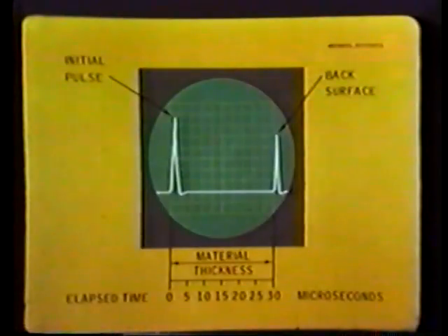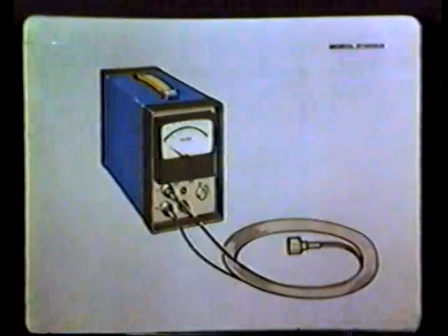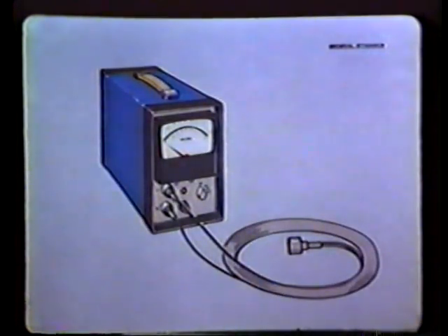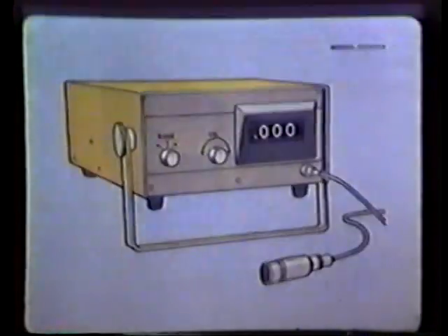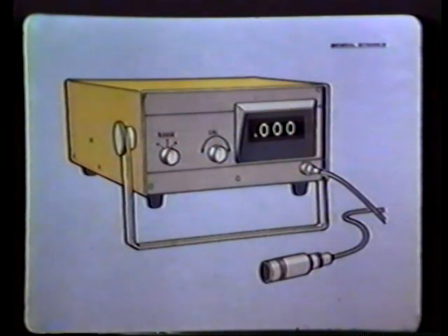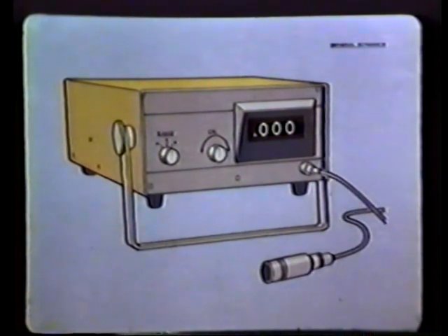You'll recall that in addition to discontinuity detection, ultrasonic sound is used to measure material thicknesses. Many ultrasonic instruments are designed specifically for thickness gauging, the thickness appearing either as a direct meter indication or a numerical readout on a digital counter. Simplicity of operation is a key feature of these instruments. Calibration is generally accomplished through a simple screwdriver adjustment or knob setting.